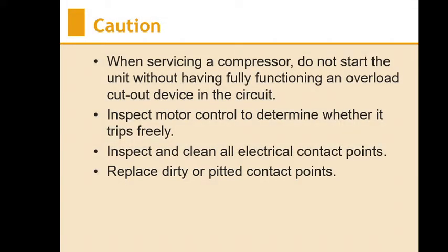Caution: when servicing compressors, do not start the unit without having a fully functioning overload cutout device in the circuit. Inspect motor controls to determine whether it trips freely. Inspect and clean all electrical contact points. Replace dirty or pitted contact points.